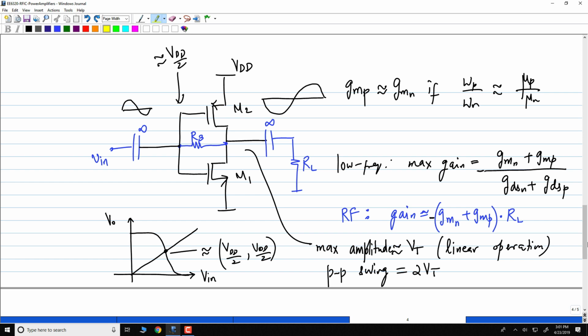But it's not the resistor that's changing the phase, it's the transistor that's changing the phase. What does that mean? Actually, I don't understand. See, this resistor will be large enough such that for AC it will be almost an open circuit. It need not be, but it's a large biasing resistor. You can choose it to be small also. So as he's pointing out, there is an AC current flowing through RB. That is all.